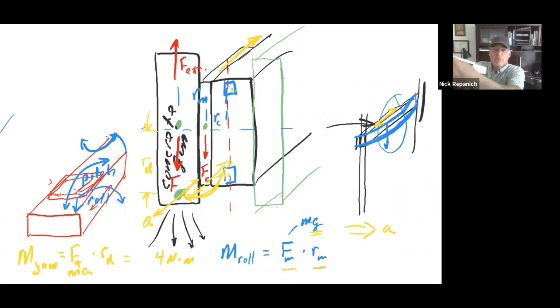The yaw moment would be the twisting moment on this, or the twisting moment this direction on that. That would be yaw. Pitch would be this direction. Roll would mean this direction. This works pretty good. And then yaw is this way, right? So in this case, since we have the mass down here, it's creating a yaw moment on this bearing. Make sense?